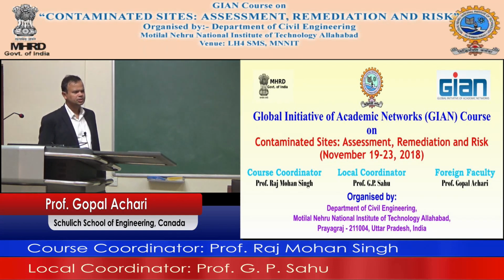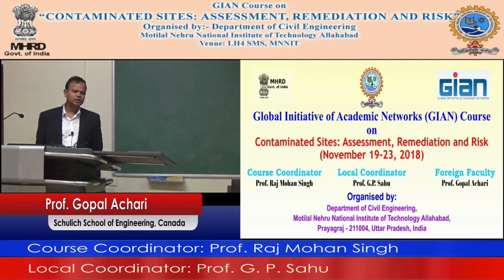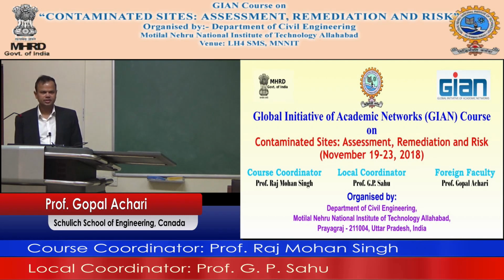One is a desorption process, the other is an incineration process. A desorption process is where you take the soil, you heat it to a particular temperature, and you get the contaminants out of the soil and then dispose of the soil. Okay, so it's done at a lower temperature compared to incineration.